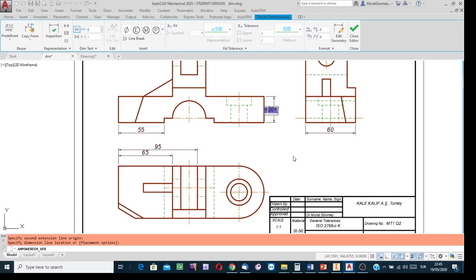It is valid in AutoCAD and it was also valid in hand drafting. What is that? Replace the wrong dimension, although the projection is still wrong in size, with the correct value, but in doing this don't forget to underline it. Then see how. First press the backspace button.